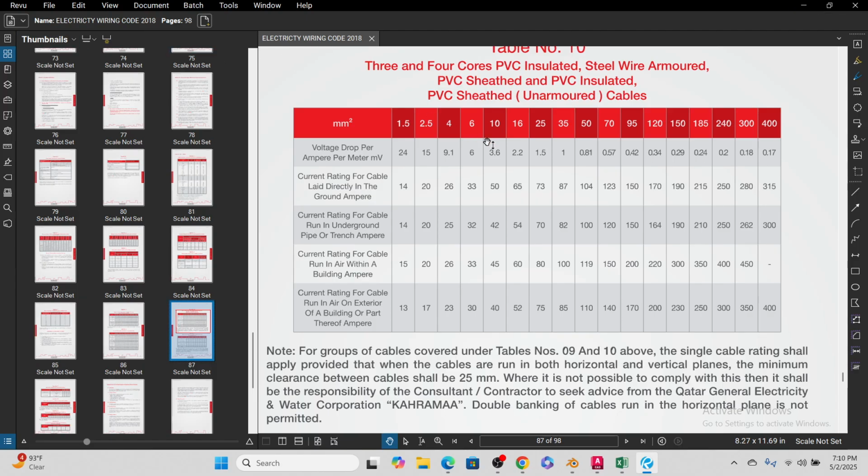I have 40 ampere here, but I will not use 40. I will go for the 60, but the actual I need is 40. Okay. So if you go here, see this one, 33 and 50 between. So 40 is between 33 and 50. Okay. So I want to use 60 ampere MCCB, so I can go for the 4 core 16 wire. 4 core 10 is enough, but still I will go with the 4 core 16 for two reasons.